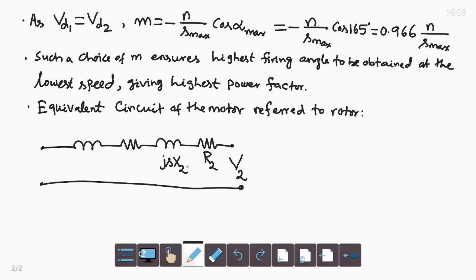And because we have taken the rotor EMF at slip frequency, the reactance is jSX2, and at the input side the voltage is S V1 by N, because V1 is the stator applied voltage, N is the stator to rotor turns ratio. Then at standstill condition, stator voltage referred to the rotor is V1 by N. When the motor rotates with slip S, the EMF in the rotor circuit becomes S times. So, the stator applied voltage referred to rotor becomes S V1 by N.